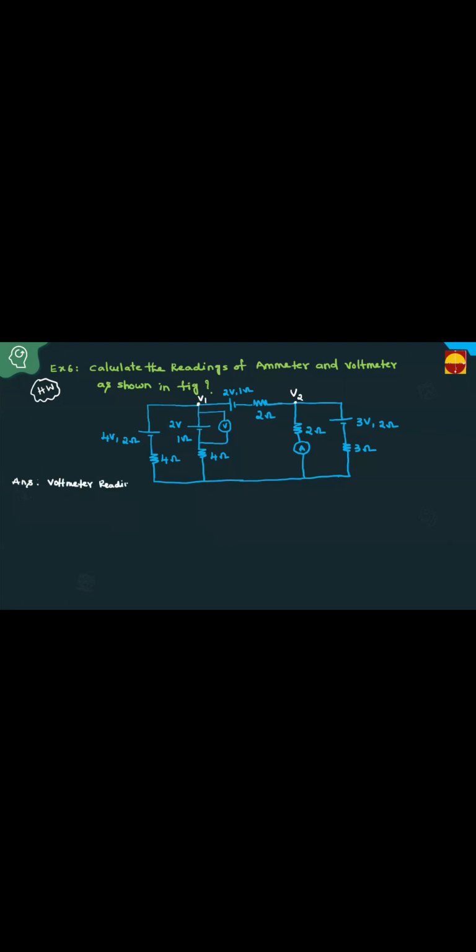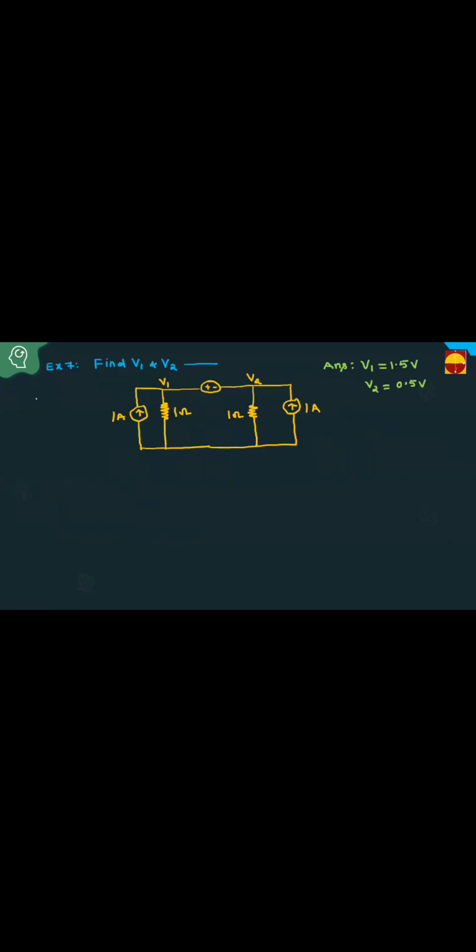The voltmeter reading for this case equals 2.1178 volts you can get. Ammeter reading equals 0.434 amperes. Yeah, this you try for practice. That is homework. And this question also you try for homework. This is 1 volt. What concept can you apply? Normal nodal analysis or super node?